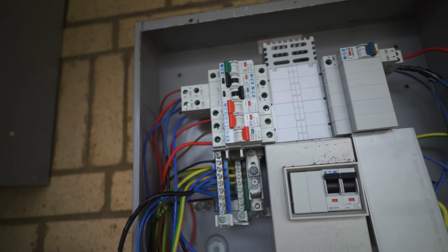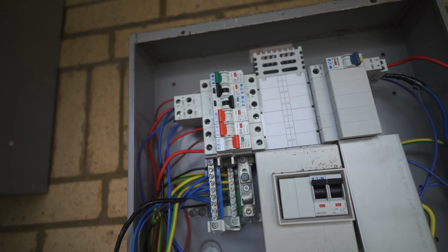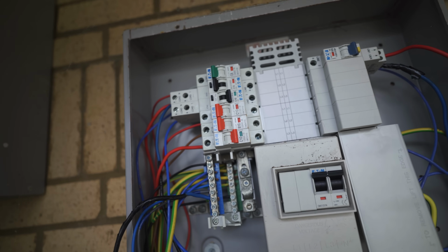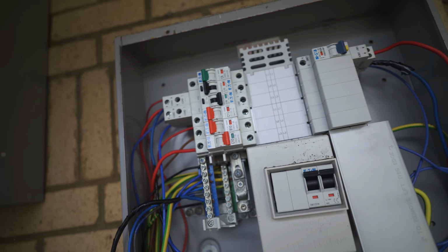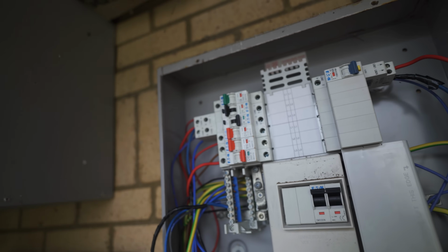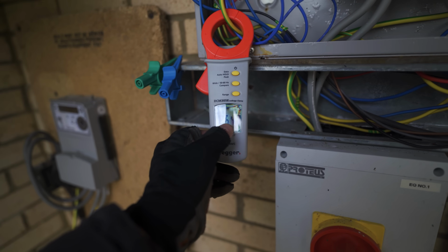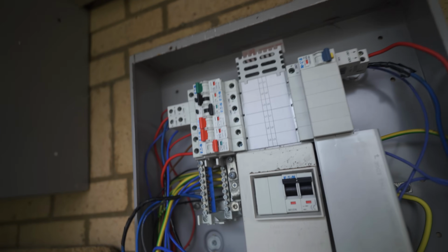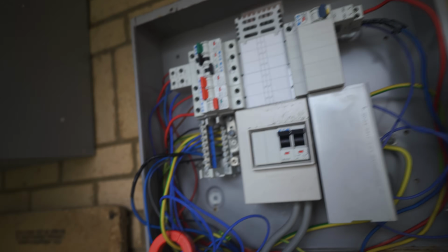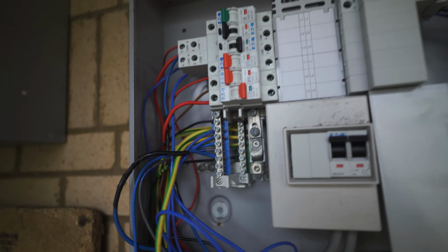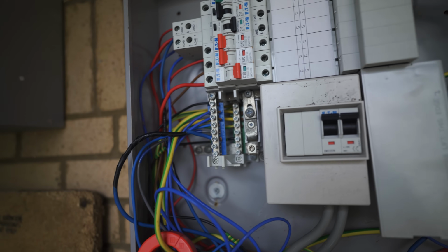I've ramp tested that RCBO. It trips at 21 milliamps, so it's a little bit low, but they all trip around that, to be honest. They all trip a little bit prematurely, so there's nothing wrong with that, really. If you've got 24 milliamps to start with and that's tripping at 21, that's why that breaker's not holding. It does hold on a normal C10. All the lights are on. I've been round and looked at them.